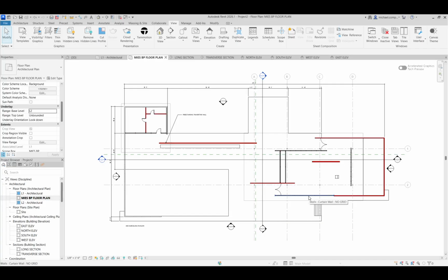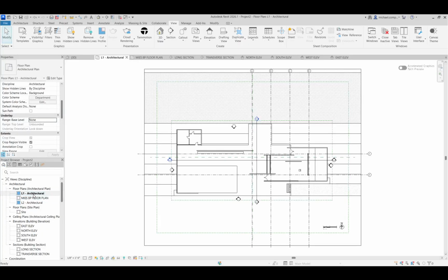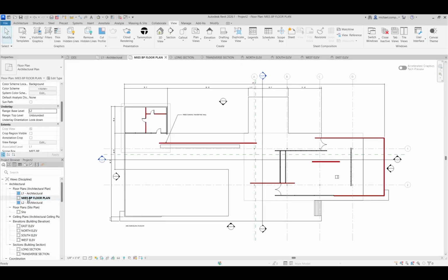Now this is the first time I think I've introduced this technical content. Everything up to now has been modeled except for the dimensions. The dimensions and the annotations are view specific. They would not exist in any other view. So for example, if I were to click on architectural, no dimensions, no annotations. So those are specific to this floor plan. Same thing with the poche, right? It's all view specific. It's also true with what I'm about to show you.